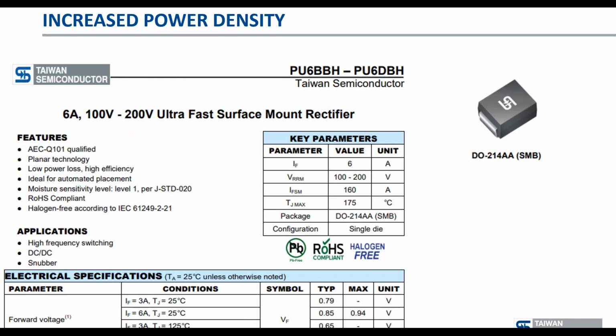So if we're looking here at the planar device, one thing I didn't mention, because the last drawing where they were next to each other wasn't particularly up to scale, is that especially these glass grooves in between the die that we etch and where we apply the glass are actually fairly big. So what we call the die size also has what we call an active area. That means the area really used, that we can contact.